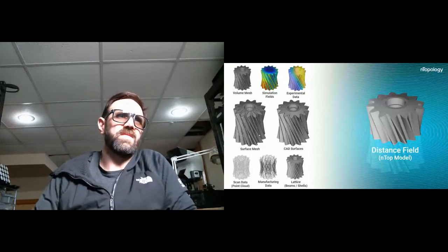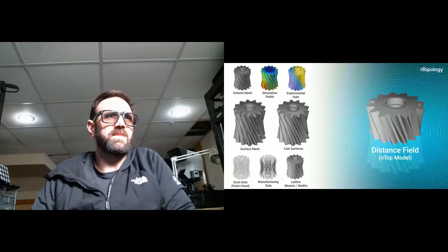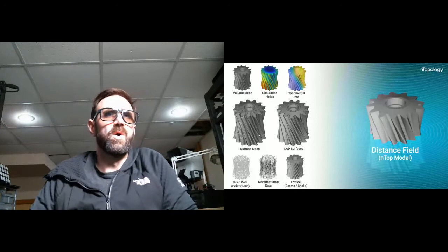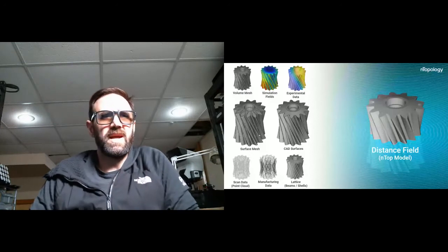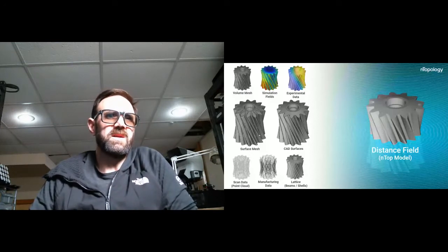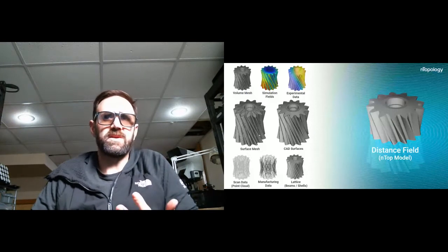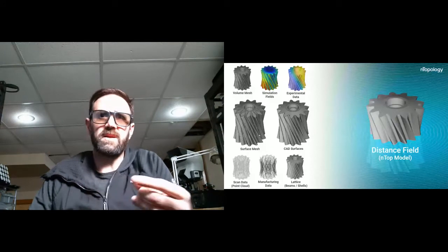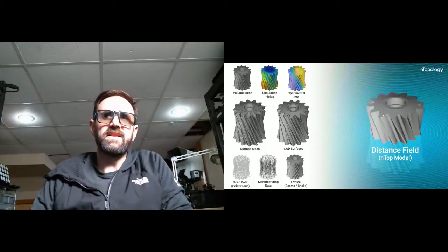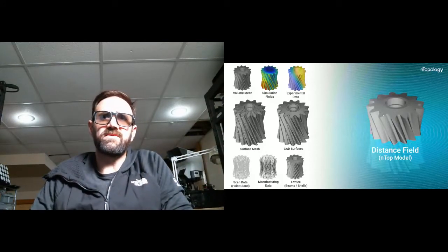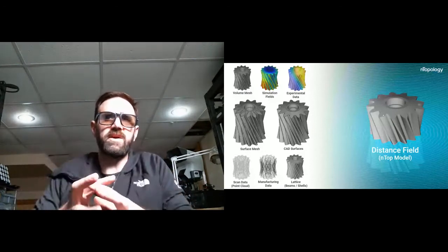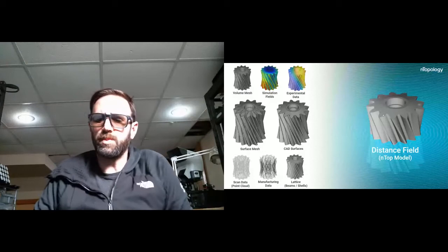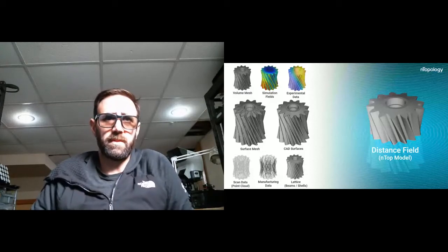And when you think about volumetric mesh and simulation, those are volumetric tetrahedrals, or it could just be point data. And so the key is that we can wrap all of these geometry types with our implicit math equation. And as we do that, we use the concept of signed distance functions. In this case, we can use these signed distance functions to visualize a distance field. And that allows us to manipulate geometry in ways that were previously impossible. And we'll talk a little bit more about that.